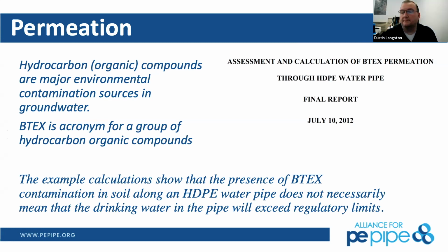Yeah, love talking about this topic. We often get the question, like you said, is HDPE pipe permeable? And you hit it right on the head. Yes, it is. HDPE pipe is the most commonly used pipe material in the oil field for oil and gas gathering. So even though it is permeable, we understand the effects, we understand how to design for it, and it's the main pipe for actually conveying gas and diesel and oil products.